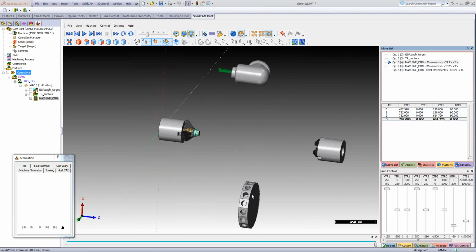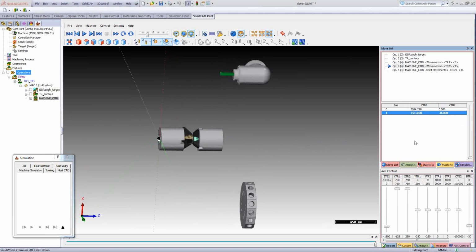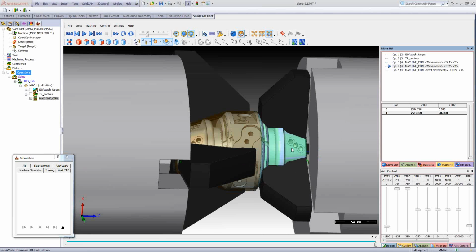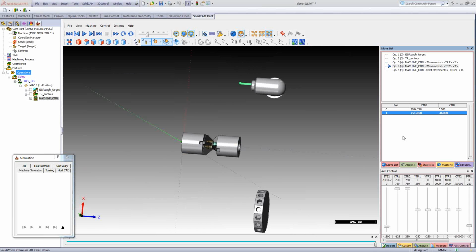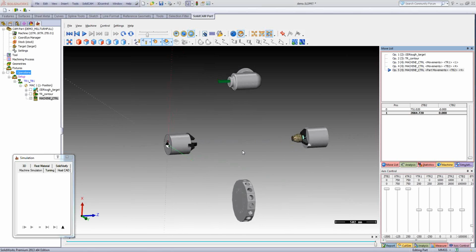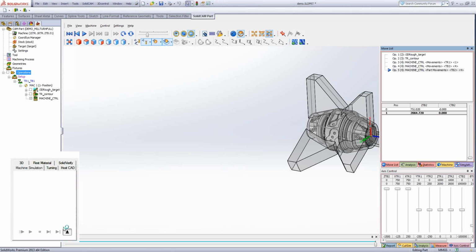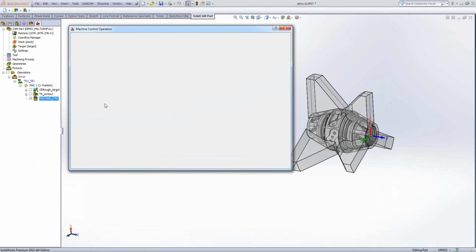The same can be done also for lower turret, a retract to a different safety position. Now the back spindle is coming and catch the part. And retract to the reference. The transfer process is done. Now we can add here in machine control something that I forgot.